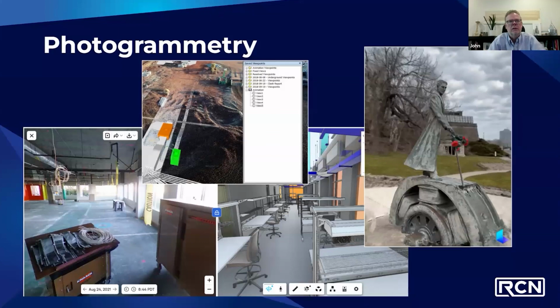If you just need to capture a comm closet or electrical closet with some stuff in there, so you can bring it into Revit and model that out, then that may fit the bill. That may get you 95% there, just using a mobile scanner. If you've got something that's got a lot more detail in it and a lot more coordination, you're obviously going to want to go with something heavier duty.